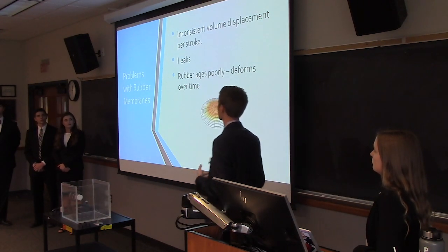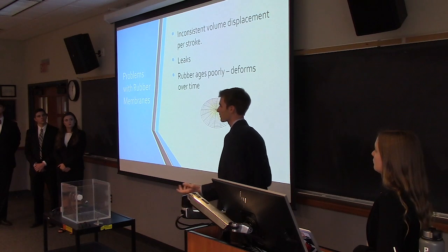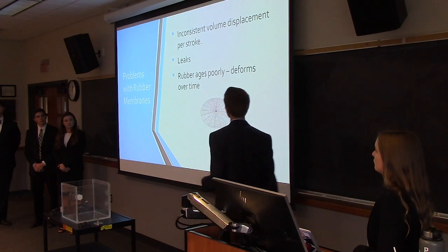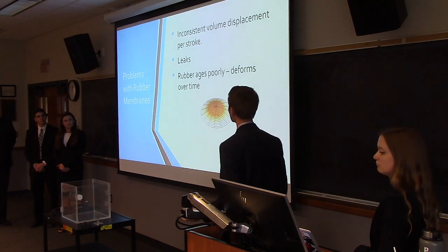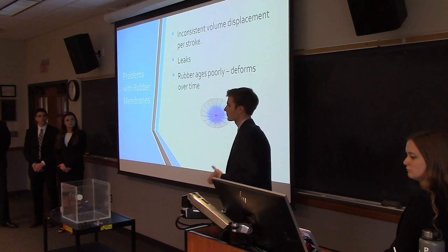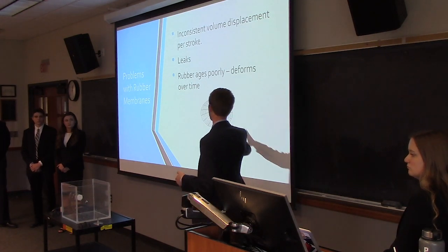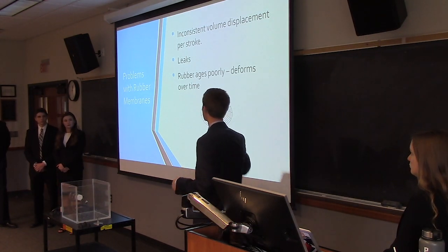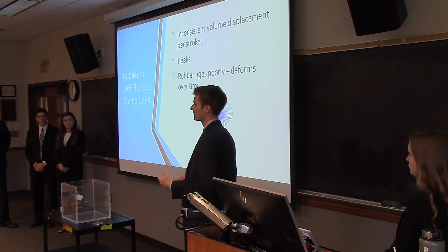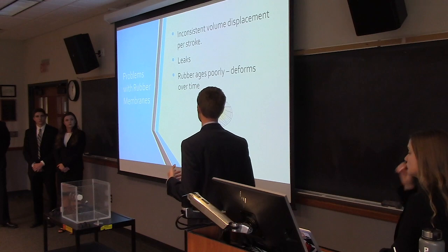The original design was from the 2013 team, and they used these rubber membranes that moved like this with the speaker. And so there were several problems. It had inconsistent volume displacement per stroke. This is theoretical, but in actuality, it kind of bent and distorted, and it was very difficult to measure the exact volume, and it was different for all the speakers.